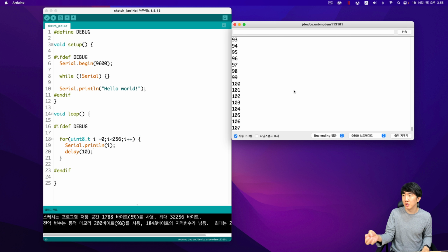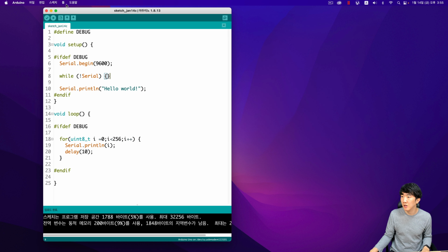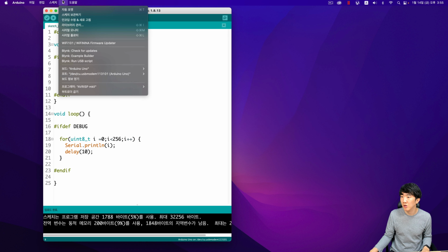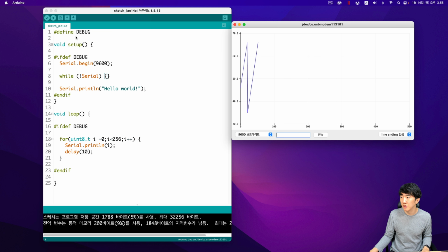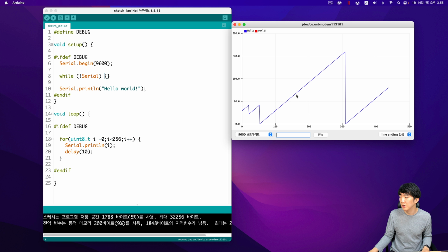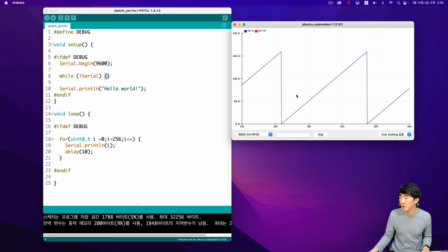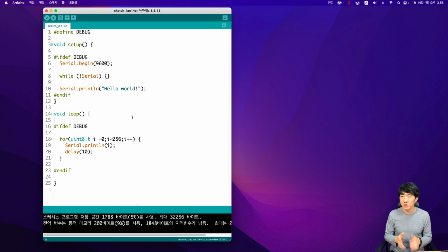If you want to visually confirm something more clearly, instead of using only the serial monitor alone, there is an additional tool called Serial Plotter available as well. If you click on that option, it displays all of your data points in a graph format. Another interesting point is that if these sensor readings are from a 6-axis motion tracking sensor, even just the gyro measurements alone would represent 3 distinct axes. There are 3 values, right?